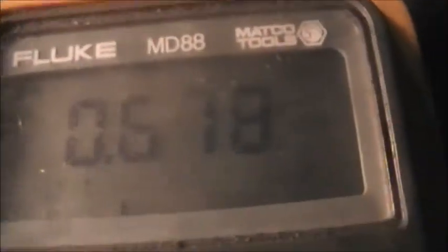Okay. Now, I have a brand new output speed sensor. I'm going to plug that in. Here's a brand new one here. I'm going to plug it into this, and we're going to see what it says. Okay, plugged into the new output speed sensor, it reads 0.67. Now this one in the vehicle was running, so it kind of got hot. This one here didn't get hot and has not been in the vehicle yet, but is reading .678.